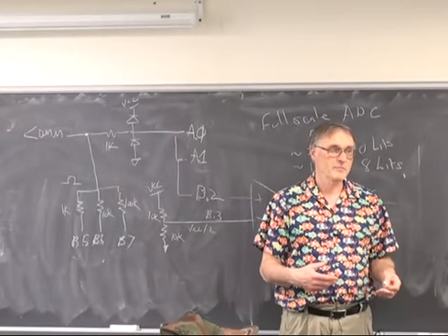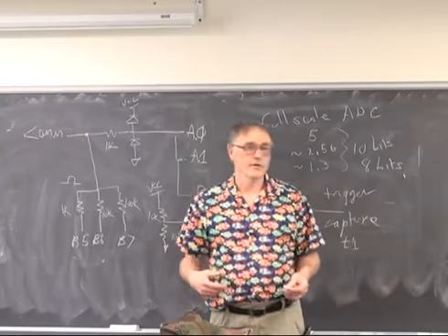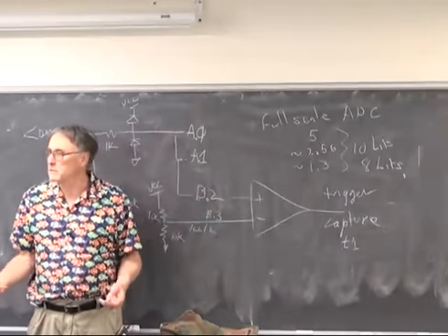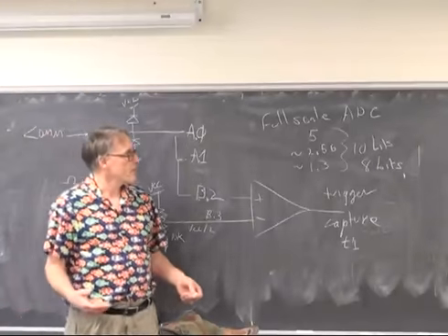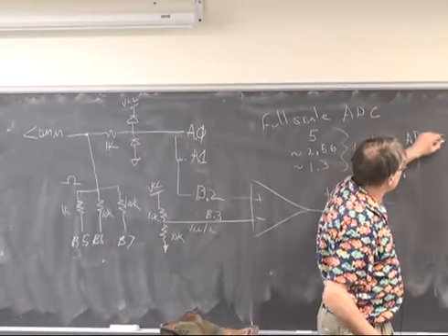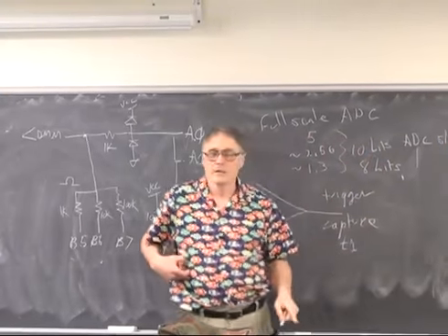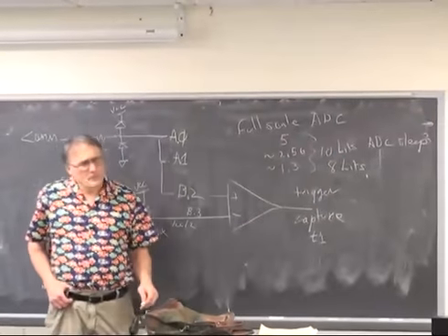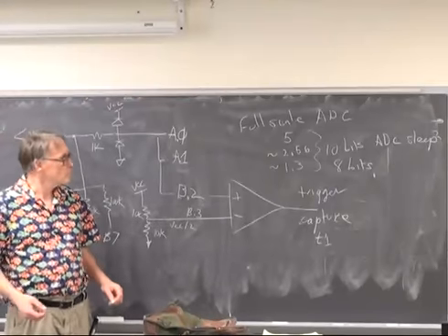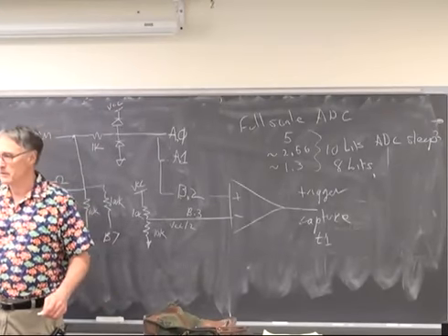This turns off the CPU for 100 microseconds. That's forever. Well, for some applications. For this application, it's just fine. So you must use ADC sleep if you want to get 10-bit accuracy. Otherwise, to get 8-bit, you have to be a little careful, but not too bad. I'm only asking you to get 7-bit.